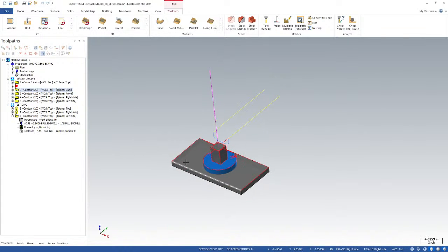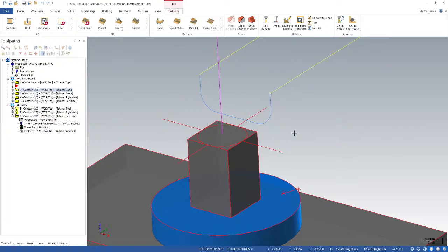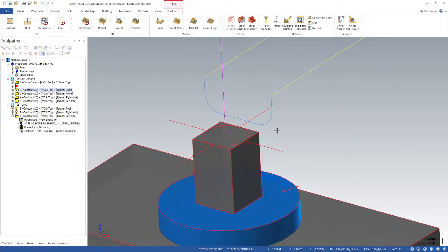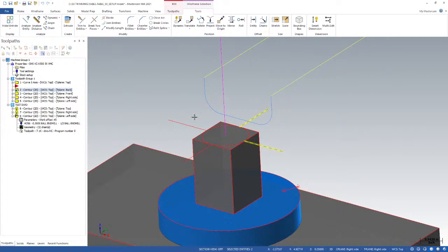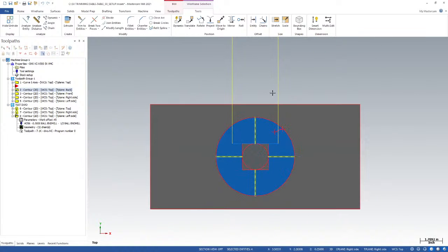So when I set up a 5-axis machine, I do the simplest geometry that I possibly can. And for me, that's a couple of things. I want a drill operation where, if I am looking down from the top of the machine, I am drilling in these 4 different axis directions towards the center of my part. So if you imagine coming from the outside and drilling in.